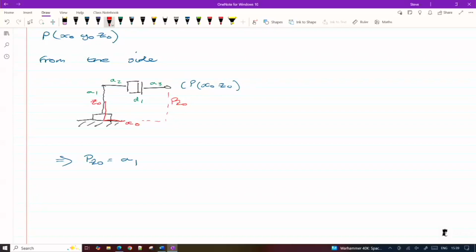Yeah, indeed. So you could immediately jump to the conclusion you can get an equation for that for x0, which would be a2 plus a3 plus d1, and then rearrange for d. But what happens is your view of a2, a3, d1 changes as your base frame rotates.